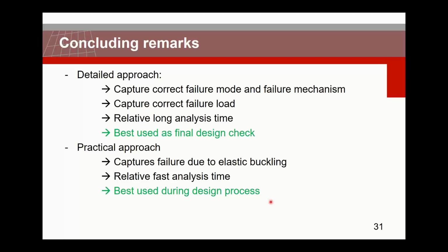Then the practical approach. The practical approach is of course based on elastic buckling. So it does capture elastic buckling quite well. It's relatively fast. And when you use the lower bound approach, it is of course a little bit more conservative, but it still describes the behavior quite well. And I think this is then best used during the design process when you're changing your design more.